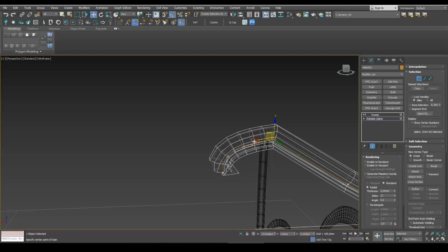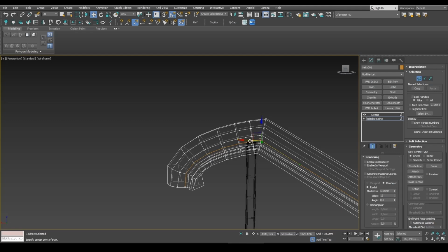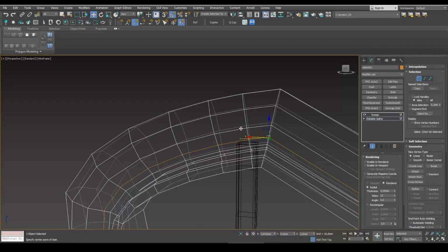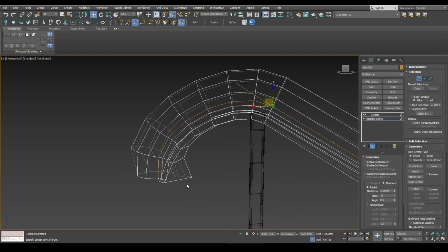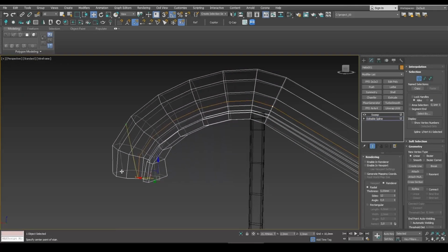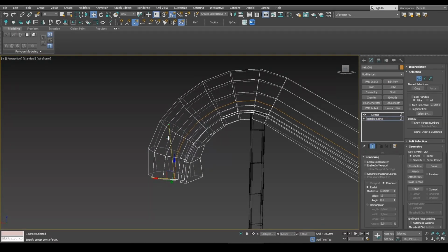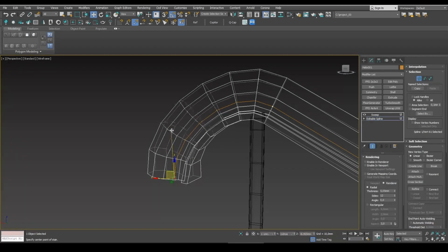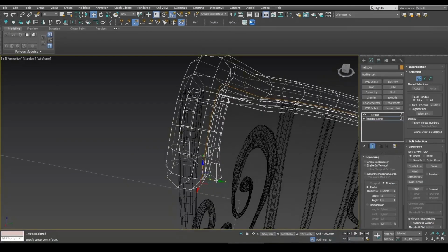So we switch them to Bezier corner, reduce this distance, and then we do a left mouse click between the axes and raise this point. Looks like the radius is too small, so we decrease these tangent vectors here, and slightly move the object.